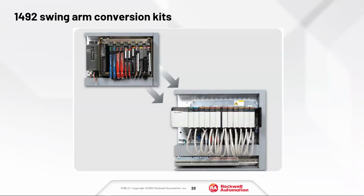This is what the conversion kit looks like. So you see in the top left, you have your PLC 5 in place, and then what you do is you essentially take the rack power supply out, you remove the IO modules, and you remove the terminal blocks. You take all the IO modules out as well, and then you reland. You can't really see it on this picture, but on the ControlLogix chassis there, you reland the field wiring from the PLC 5 terminal blocks behind the ControlLogix in a conversion rack.